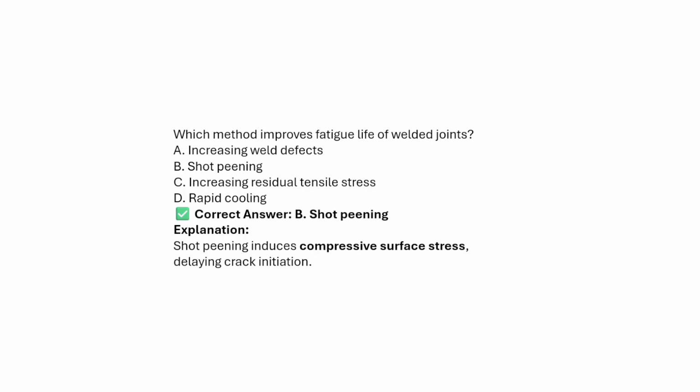Which method improves the fatigue life of the weld joints? Increasing the welding defects, shot peening, increasing the residual tensile stresses, or rapid cooling. So the answer will be shot peening. Shot peening introduces the compressive surface stresses that delay the crack initiation.